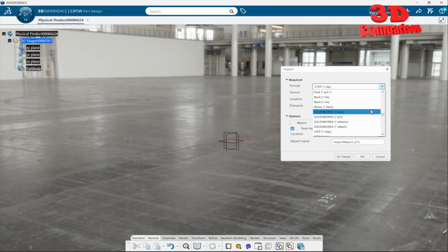And over here, I can change through various file formats. So we see over here, STEP file. We can also have that STL file. So CATIA has a lot of file formats that can be imported. But as we scroll over here, we're going to see that the STL, which is quite common, especially due to, let's say, the popularity of 3D printing, will not be available over here. So we have the IGS, which will also include some surfaces, but STL file, as you can see, won't be over here. So in order to import the STL file, you need to do the following.